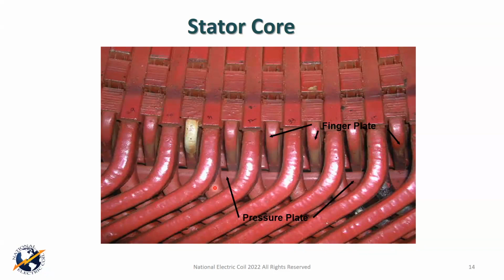When we have problems and you have to try to do a repair or patch something, it's a little more than that, because the top coils always go one direction, and it could be either way depending on the design of the machine, and the bottom coils go the other, and they form a big knuckle to give you your full end volute here on the ends. That's just a good picture to show that.